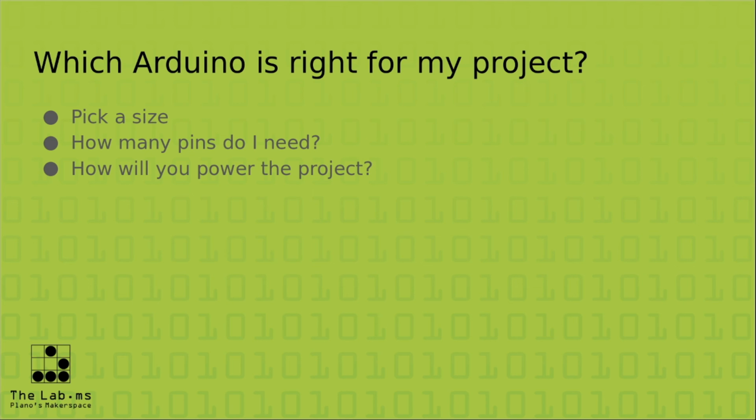There is quite a range of sizes. There is the Arduino Uno, which is the typical size. It is a credit card size board. There's the Arduino Mega, which is about twice as big as that, and it's got a lot more input-output pins. And they go all the way down to, I believe it's the Gemma, which is about the size of a quarter, and it has about 5 or 6 I/O pins. And you can actually run that thing off of a coin cell battery. So there's quite a range of boards that you can choose from.